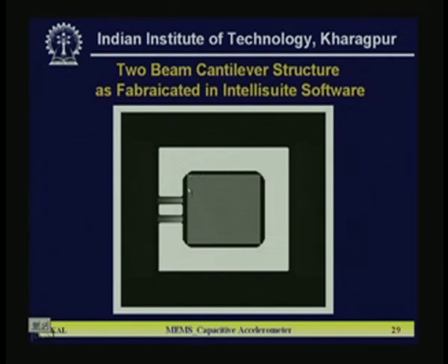So sometimes a compensation, called corner compensation, is given, so that although the corners etch faster, in the end it should look like almost a square frame. That is why a compensation like a rectangular piece is added here, so that after etching the whole structure will be as rectangular, as square as possible, with the flexure at the center of the cross section.